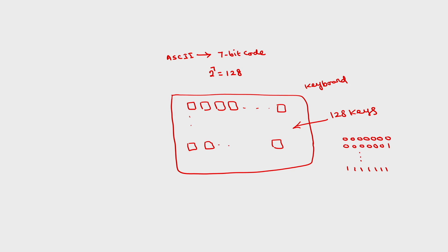So in the case of ASCII code, 0 is represented by, this is standard, 0 1 1 0 0 0 0, which is 30H. This is in hexadecimal, you can even insert a 0 here. So this will be equivalent to 30H. 1 will be represented by 31H.